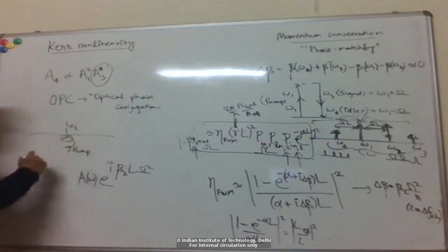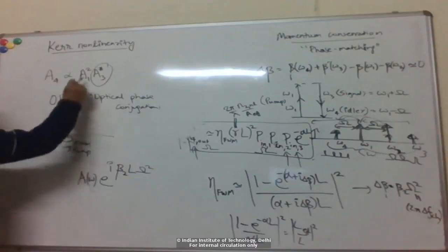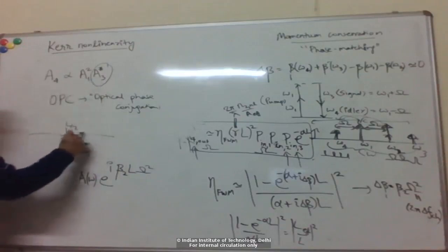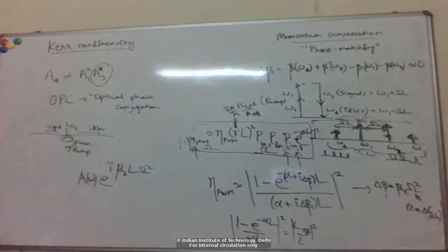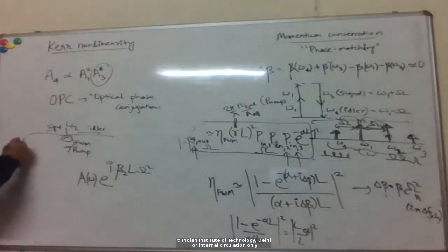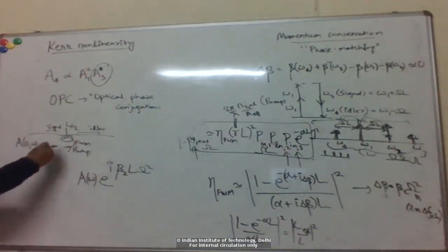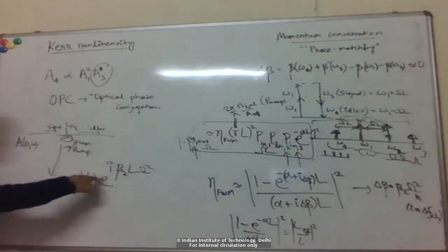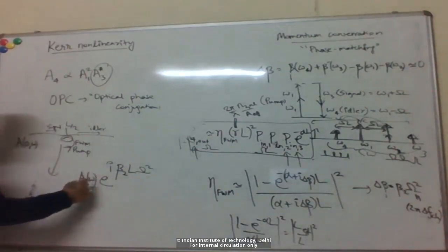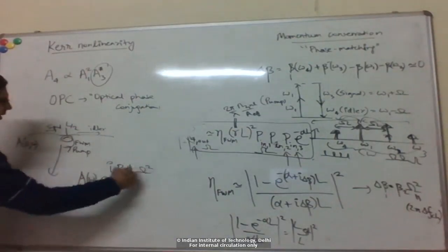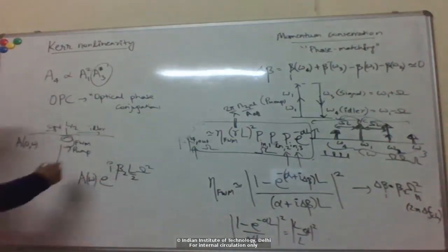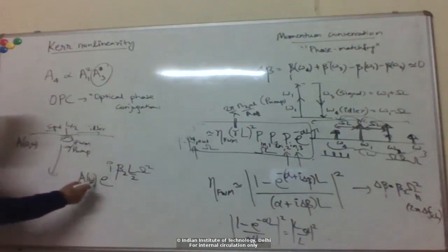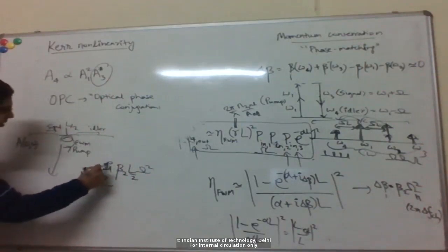Locally you have a strong pump wave here, and you do four-wave mixing, and you send forward the idler from there on. Your input had some spectrum, and at the halfway stage, due to the dispersion, you multiply by a phase like that. Now due to this four-wave mixing, the idler that you generate is the conjugate of this. So you take the conjugate, and you get a minus sign.